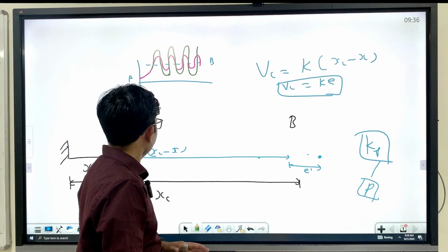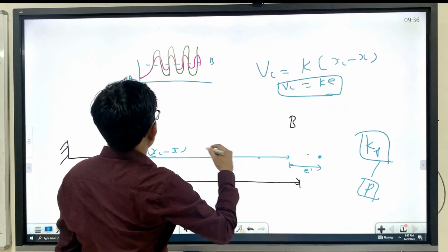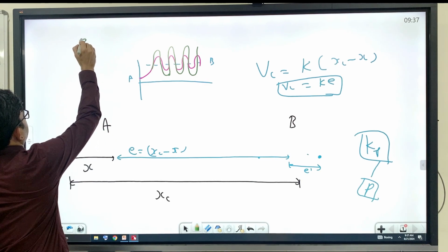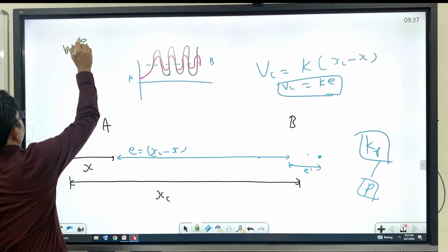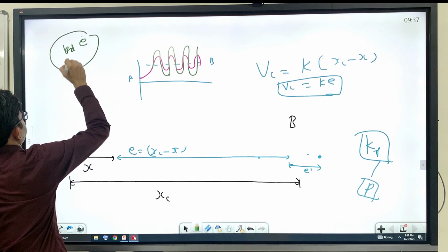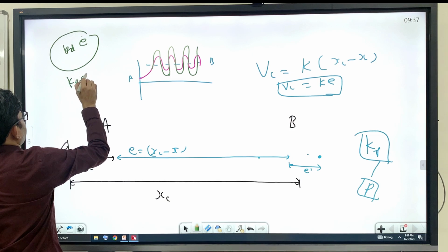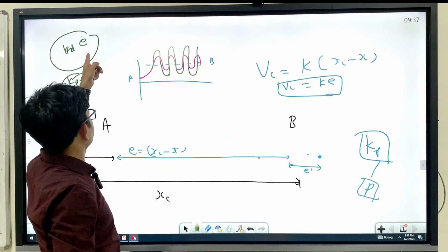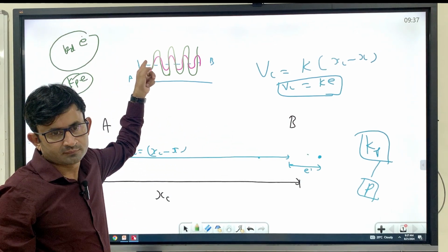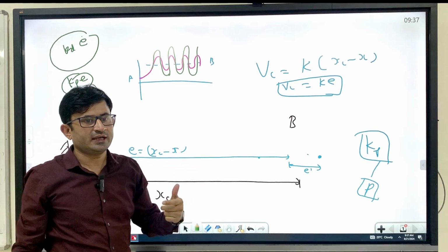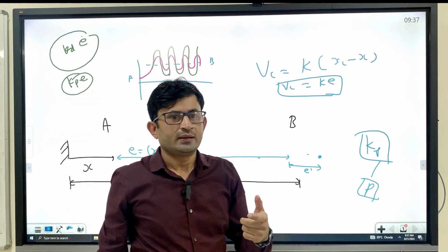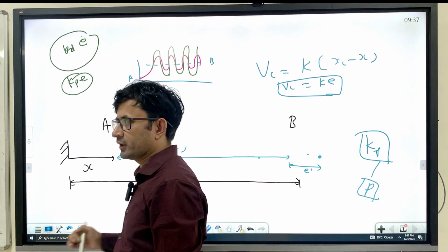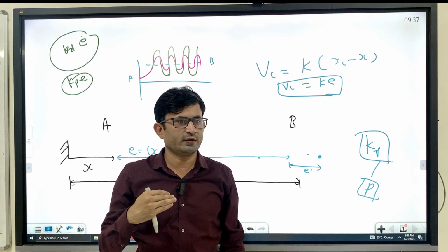Now, when you take E dot, for example Kd into E dot, see Kp into E is the proportional part, now I will add Kd into E dot. That means you are controlling the rate of error. If you differentiate, basically you have control over velocity.